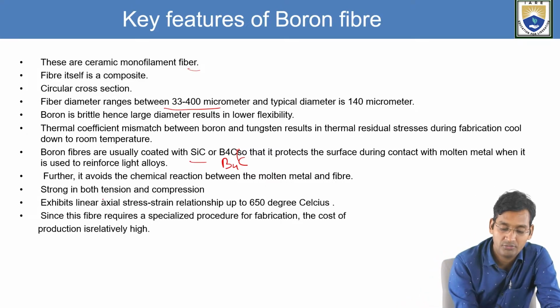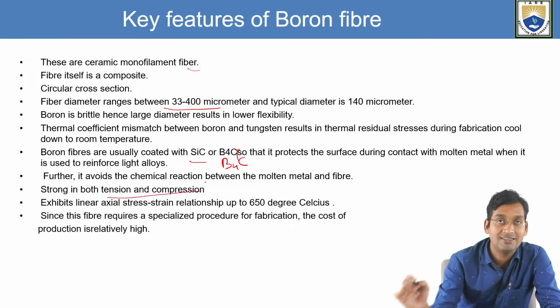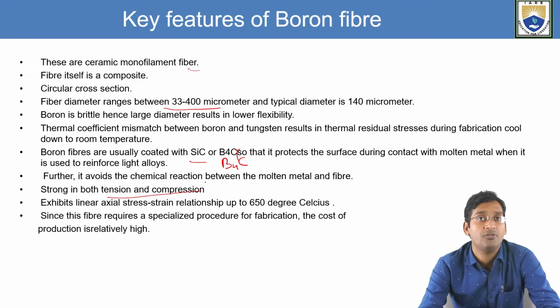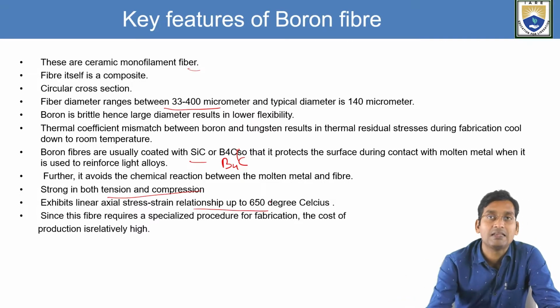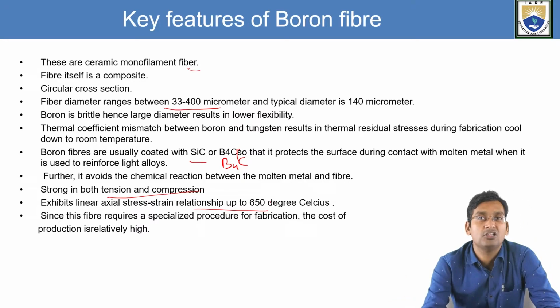So boron fiber is strong in both cases, either tension or compression. It exhibits a linear axial stress-strain relationship up to 650 degrees Celsius. Means it will obey Hooke's law, that linear stress-strain relationship, up to 650 degrees Celsius.